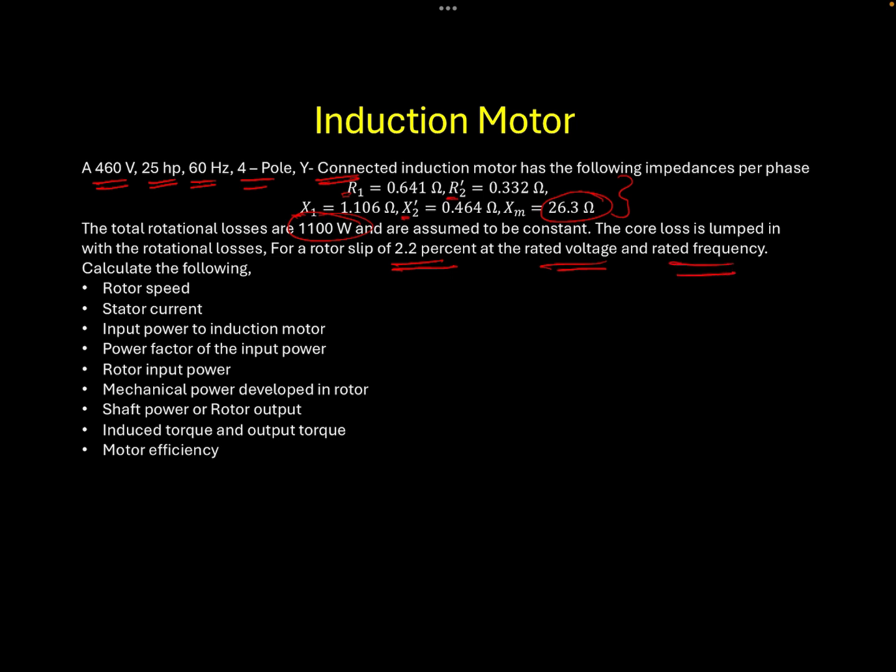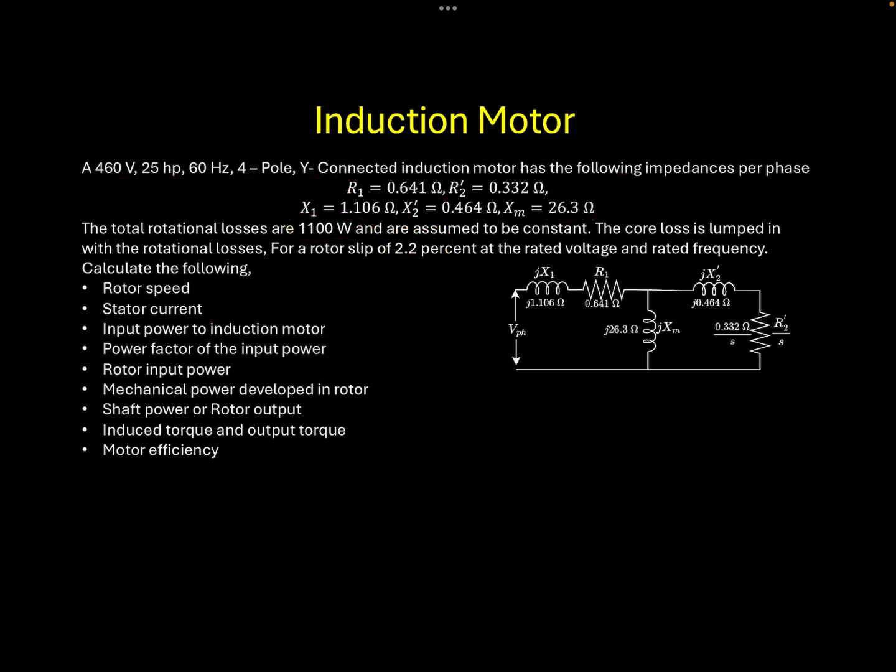Now in this problem, we need to first calculate the rotor speed, which can be calculated from the synchronous speed as well as the value of the slip given. And we need to calculate the stator current and input power to the induction motor and power factor of the input power. In order to calculate these three values, if you look at the equivalent circuit of the induction motor,